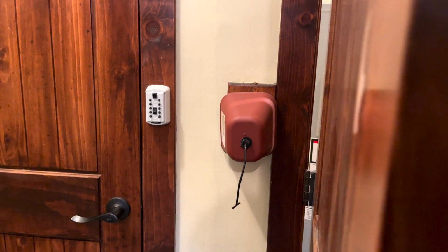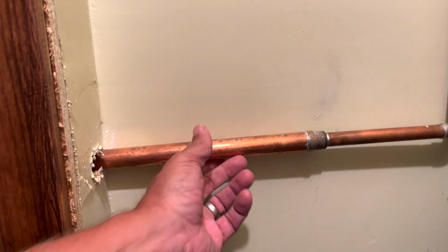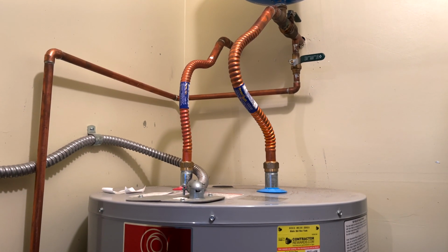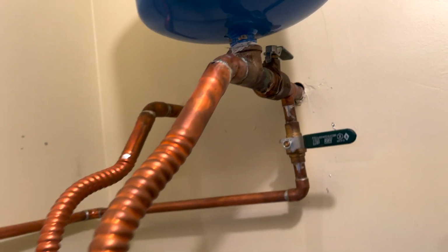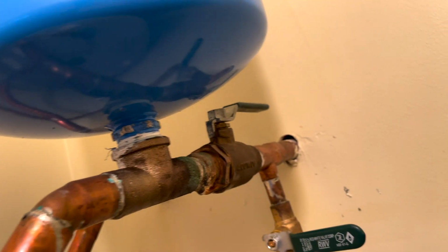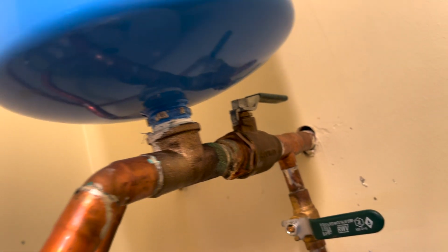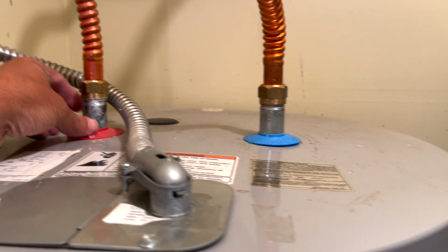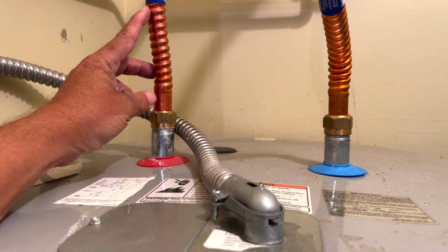There's the water source there, frost-free hose bib coming from the main line by the expansion tank above the hot water tank. Well, it's not a hot water tank, it's a water heater tank, right? There's the main water shutoff valve. We've got a leak there. We got a corrosion leak. The corrosion has sealed off the water leak. Cold water in, hot water coming out.